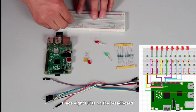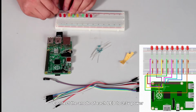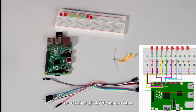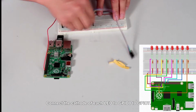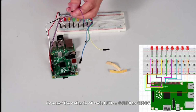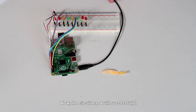Now, let's build the circuit. Place 8 LEDs on the breadboard. Connect the anode of each LED to the 3.3V power source through a 220 ohm resistor. Connect the cathode of each LED to GPIO0 to GPIO7. Now, the circuit has been built successfully.